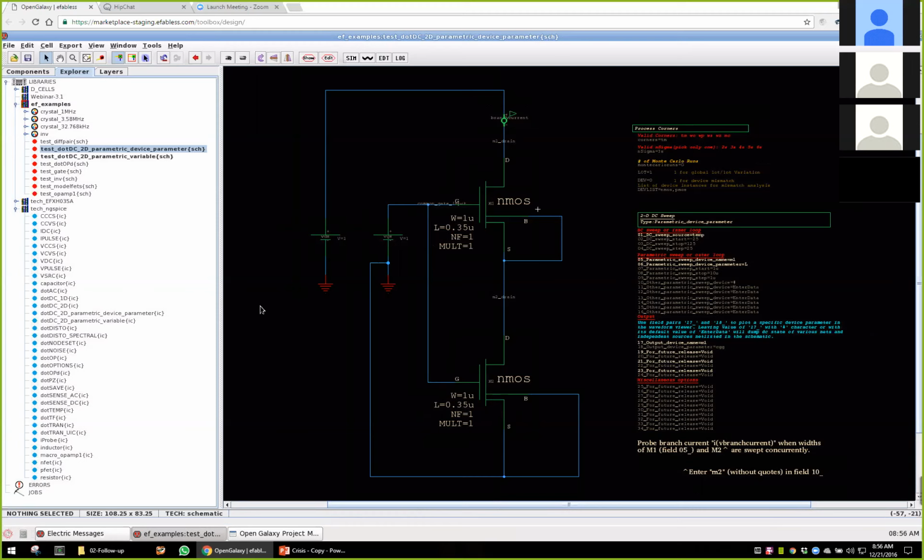Can you cut the feedback system, make it an open loop system, plot the Bode plot, and then manually visualize the stability, looking at the phase? Yes, but I think you have to maintain the operating point, and also you have to take the loading effect of the different parts of your circuit that you're going to cut.